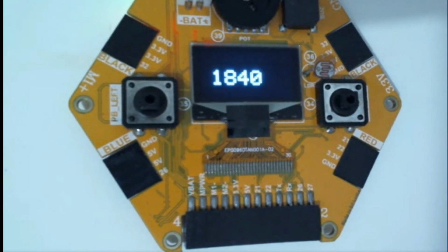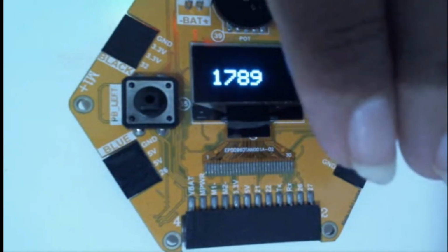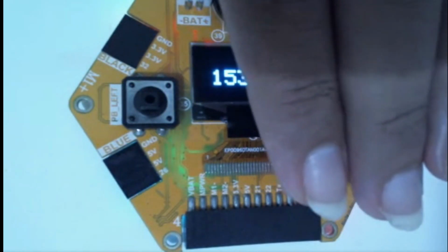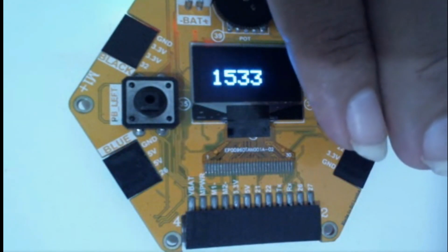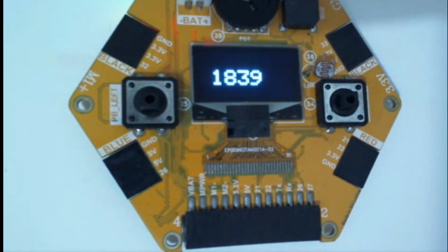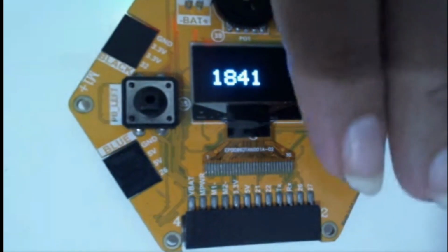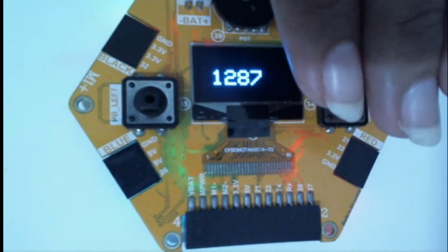That means as I have turned on the lights in my room, this LDR here is detecting that light. So if I cover this LDR with my hand a little like this, then the amount of light rays falling on the LDR will decrease. So can you see now the value on the screen is getting lower, right? Earlier, when I removed it, it was like 1800. When I cover the LDR like this, the value is getting low.